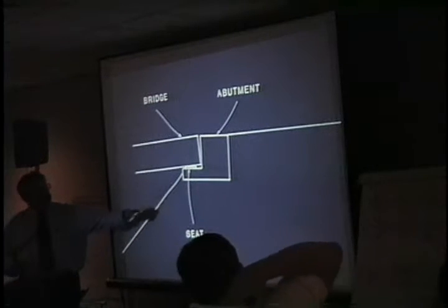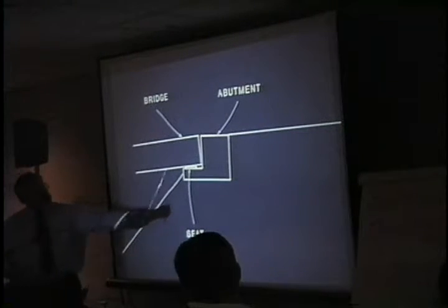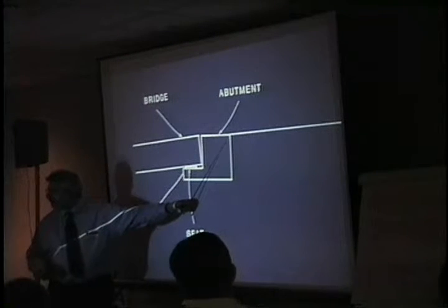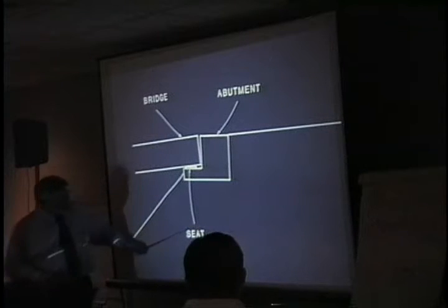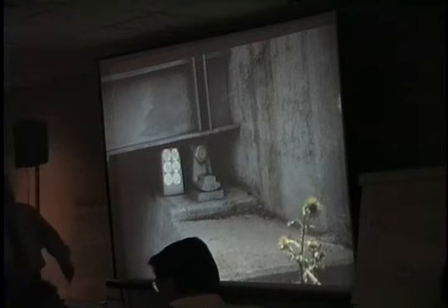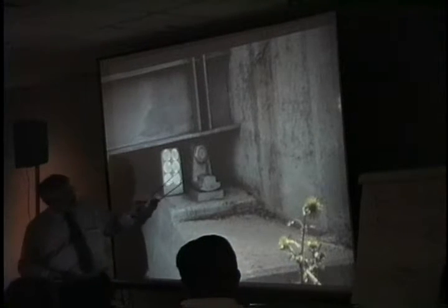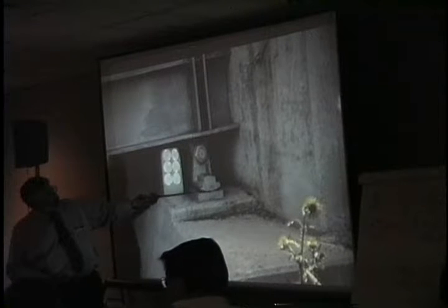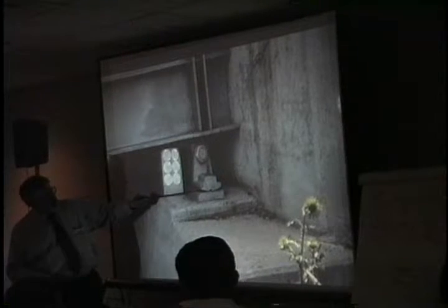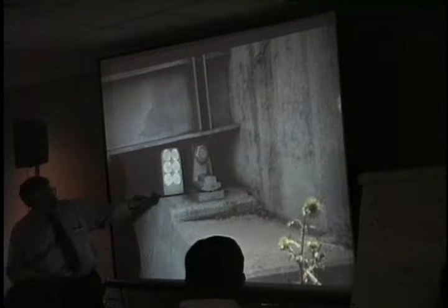This is an indication that this abutment has rotated back, correct? So there might be a slide right in back there. And here's another sign. Notice the rocker bearing is not dead center.